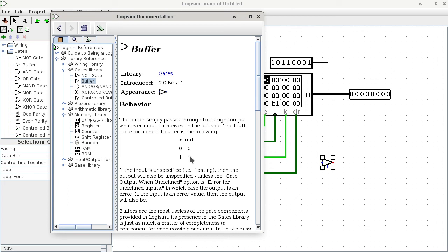Is that okay? It's kind of like a megaphone. It allows you to reach more inputs with reliability. Is it like a repeater? Does it get it and then blast it out stronger? Yep. In networking terminology, this is basically what a repeater is. I didn't want to throw out the term repeater because not everybody has a networking background, but yes, it is basically a repeater. So this is the reason why we have buffers: it doesn't seem to serve a purpose in terms of logic, but it does serve a purpose when you are doing the actual circuitry in the physical world.